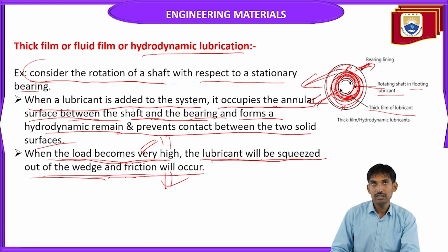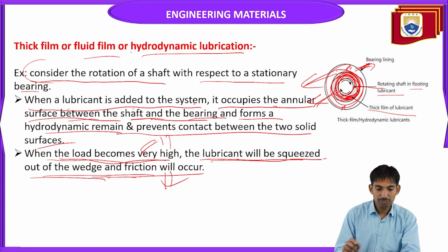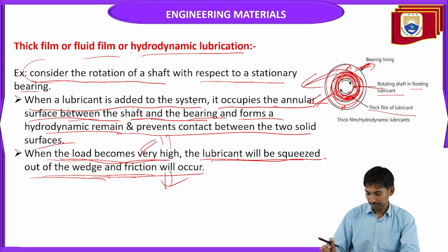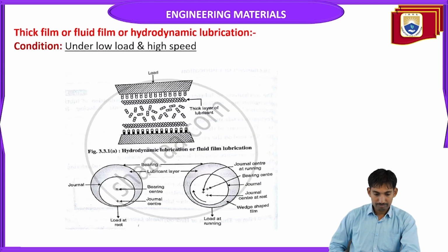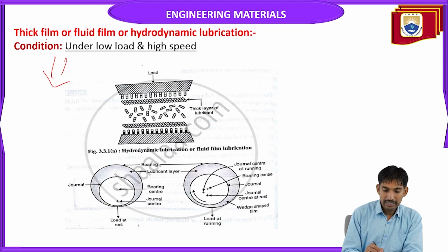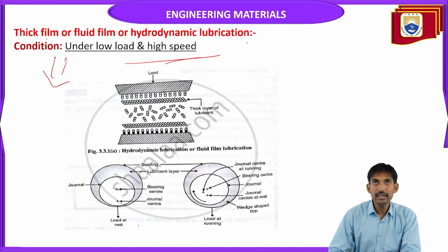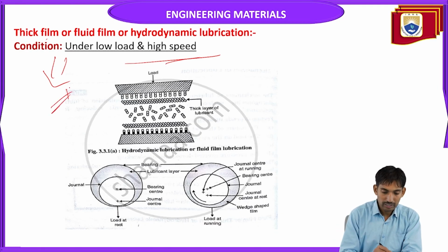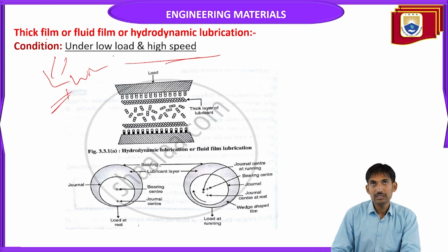In the case of thick film, fluid film or hydrodynamic lubrication, the condition is under low load and high speed. If you apply a high load, it will not work. The resistance will increase, or friction will increase between these two moving surfaces.